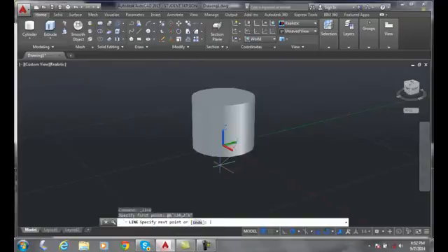And I'll say enter. And notice now my pipe is right on the edge of that cylinder at the dimensions specified. And we could use other commands to extrude that line out, etc. later on. So we use cylindrical coordinates. The key thing here is we go to our architectural units and we turn off our dynamic input, which is dynmode, dynamic mode, and we set that to 0.